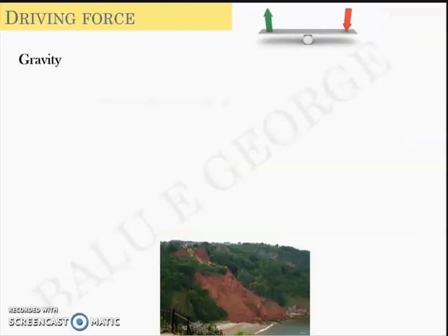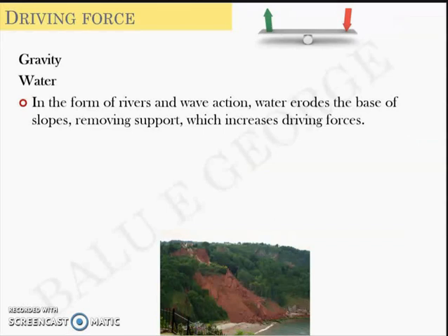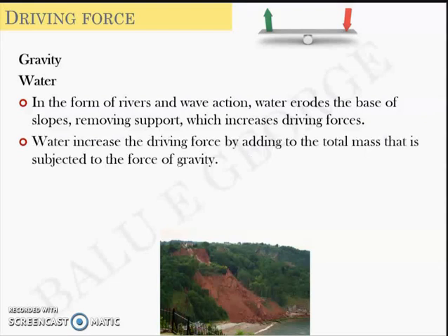The driving force. Apart from gravity, water can be a driving force, where in the form of river or wave action, etc., water tries to erode the base, removing the soil, which might induce slope failure. Another action of water is that it adds weight to the soil. We know that the bulk density is smaller compared to the saturated density. The same principle gets applied here. When water goes into the soil, the weight of it increases, thereby the force due to gravity increases.